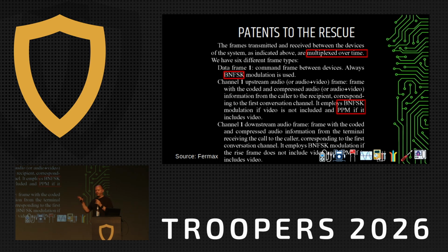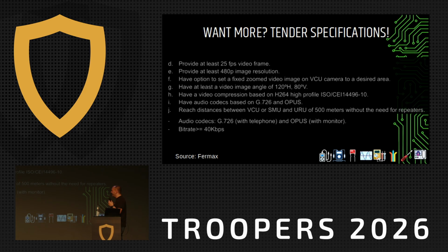Actually, before doing this project, I'd never seen PPM. I've seen pulse width modulation, but pulse position modulation is something even crazier. It basically allows for infinite data density depending on the quality of your medium. Quite a cool idea, because the position can technically be an irrational number.